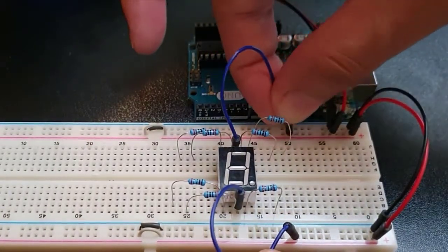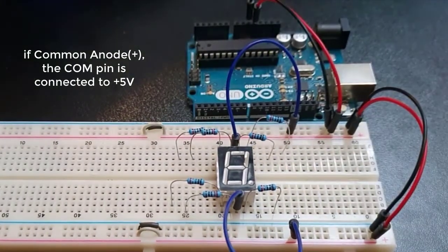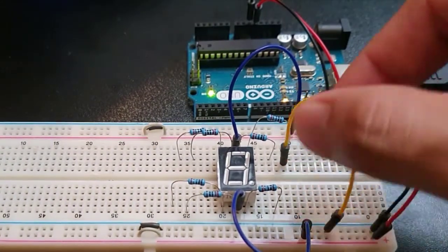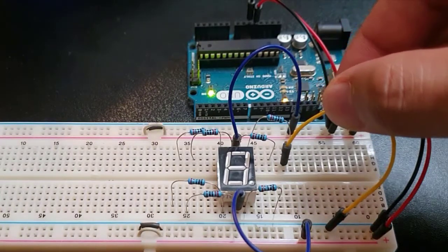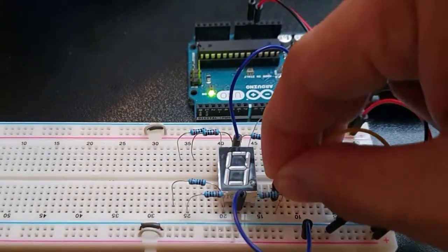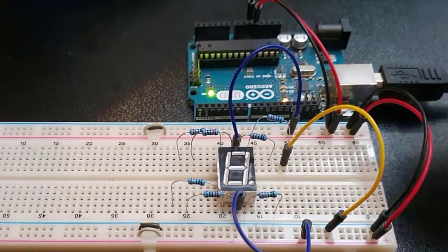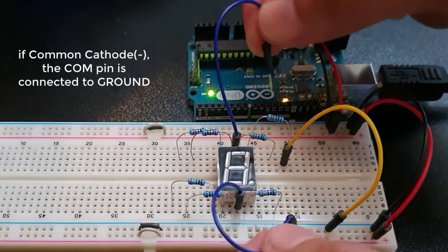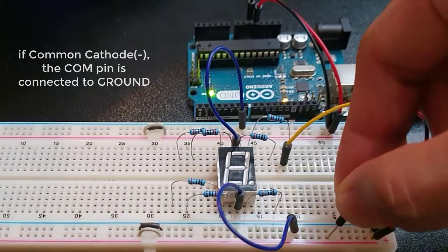So, for this example, if I assume that this is a common cathode, the common pins must be connected to ground. And to test each individual segment, I am going to connect any of these segments to logic 1, or positive 5 volts. If it emits light, then we are correct. If it doesn't, it means what we have used is not a common cathode but instead a common anode 7-segment display, and therefore, we need to reverse the connection by placing the common pins to the positive supply, and each individual segment now requires logic 0 to emit light.